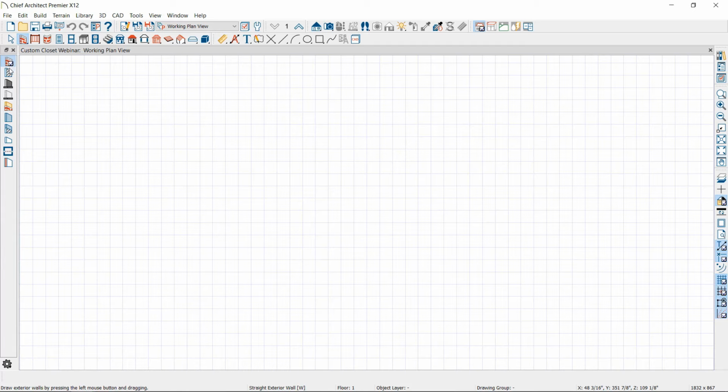So it doesn't really matter for the purposes of what we're doing today whether or not I use the exterior or the interior wall tool. This happens to be an entirely enclosed space, so I am going to go ahead and just use all of my interior walls. Obviously, if we were going to be working with framing or needing to order our framing, we would definitely need to be very particular about what wall type we're choosing, but for what we're doing, I'm just going to use those interior 4 walls.